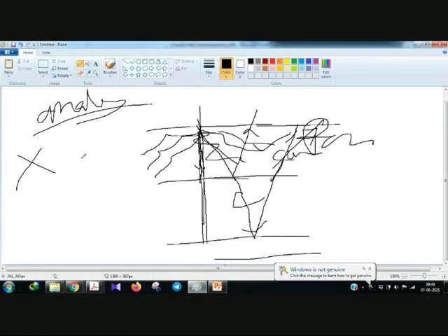So whenever you go for a GPR survey, you have to look for a dry condition. You have to avoid the wet condition of the soil, and you have to observe if it's a fine sand condition or clay material at the top, then you won't get any signal, or you will get a much attenuated signal.